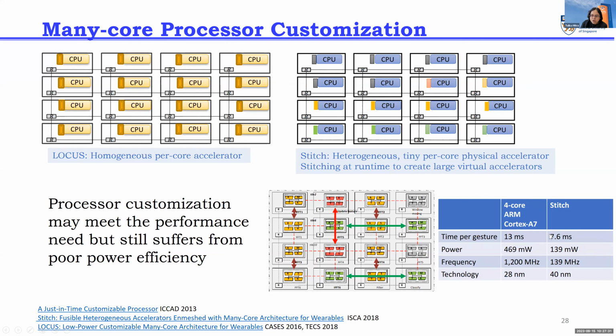So that's the data flow processor architecture, and it's not a new idea because it has been there from 1975, but it never took off. Why? Because the general purpose processors were doing so well, as I mentioned earlier. Fast forward 60 years, what we are seeing now is that data flow computing is everywhere. In fact, of the AI accelerators you can think of, a few are GPU based, but almost all the rest are based on the data flow computing model. If you look at Cerebras, SambaNova, Graphcore, AMD AI Engine, all of them are doing data flow computing. Why? Because the data flow computing really matches well with the AI data flow in the software, and so that gives us huge performance and power gain, right?